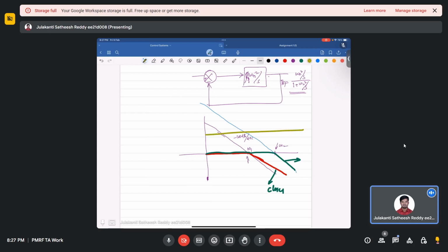So you are getting only constant magnitude there. That means it is independent of that. You will always expect some error there. So if you have a proper PI controller there, what exactly happens? You demand very high gain at the low frequencies below bandwidth, so that the error will become 0. Agree? So at these points the error is almost coming to 0. So this very high gain at the low frequencies brings the error to 0.